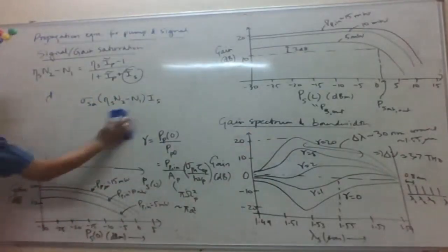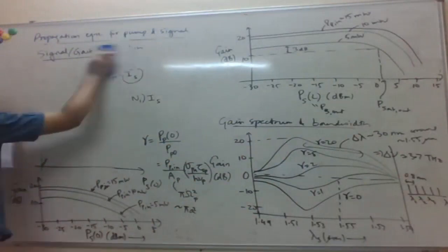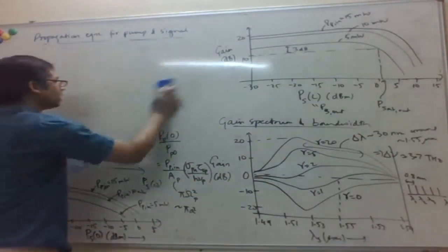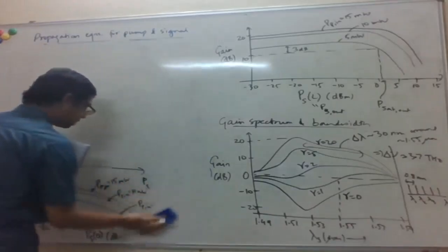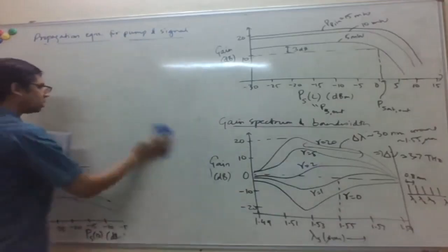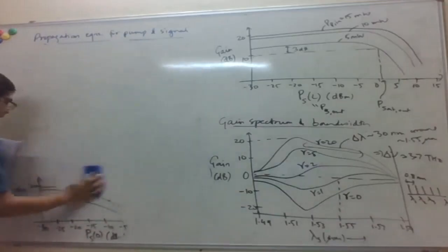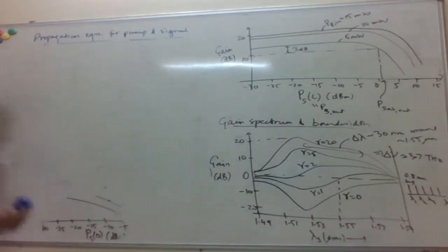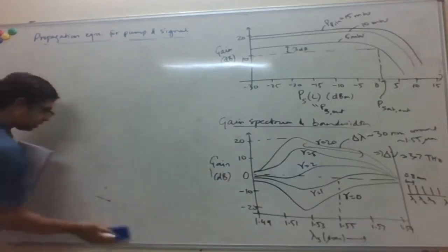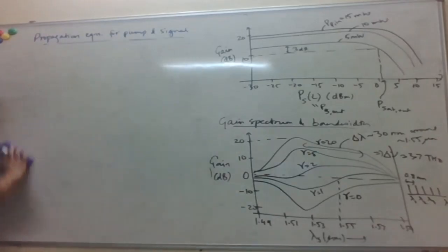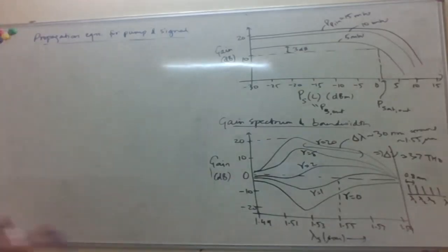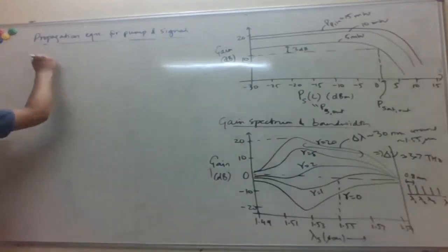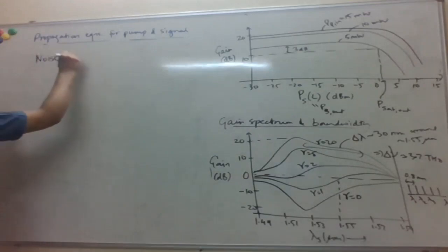And the last thing I just want to briefly mention is noise figure. So any amplifier always adds noise to the signal, right? This amplification doesn't come for free. So if you have any noise in the input signal, that also gets amplified, right? So the signal gets amplified, the noise also gets amplified, but actually it's much worse because the amplifier also adds its own noise.